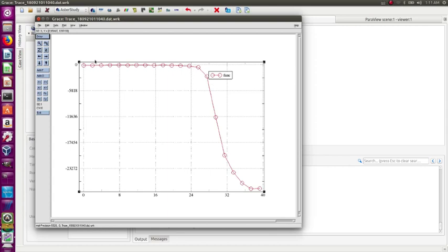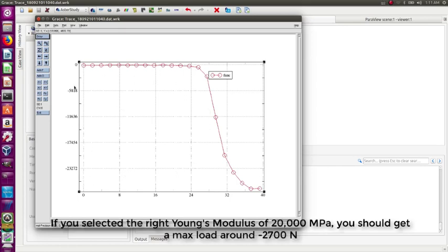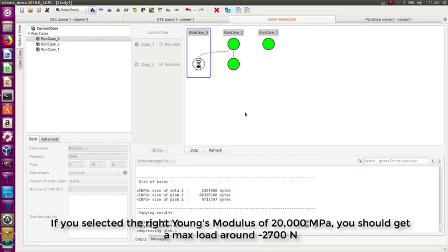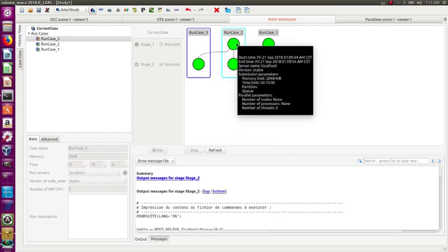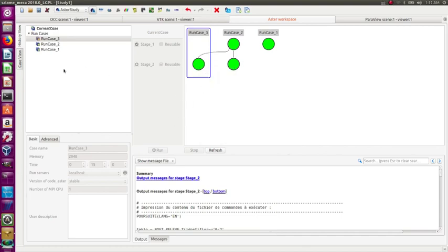Okay, so now I'm getting the pressure from this. Now I see that the unit is a bit too large, so I think I still have a small problem somewhere. Probably there is a factor 10 somewhere, probably in the material properties, where I added a 0 too many or too few. But anyway, you get the idea of how you do this. So this is the pressure at the contacts printed out in this curve. And it's very good to have this option, because you don't need to recompute the first step. You can directly compute the second step, and it's much faster.